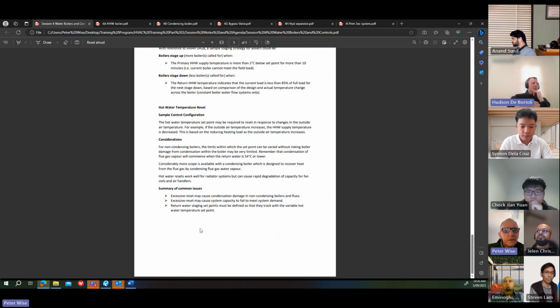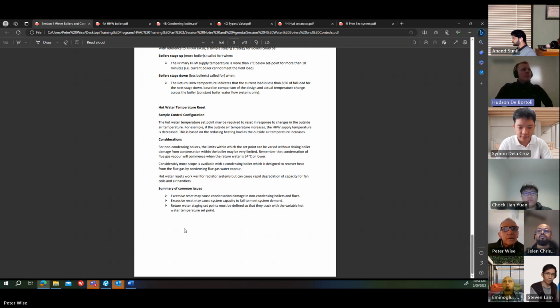It would just modulate completely. Slight modulations would have large differences in the flow. It's probably going to go up and down. It's going to try and close and open and close and open, which is called hunting. And you want to avoid hunting of valves in particular. And that's, I think I mentioned, to maintain the system stability.